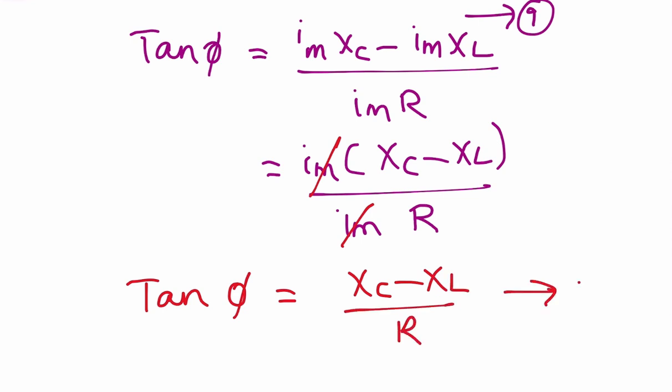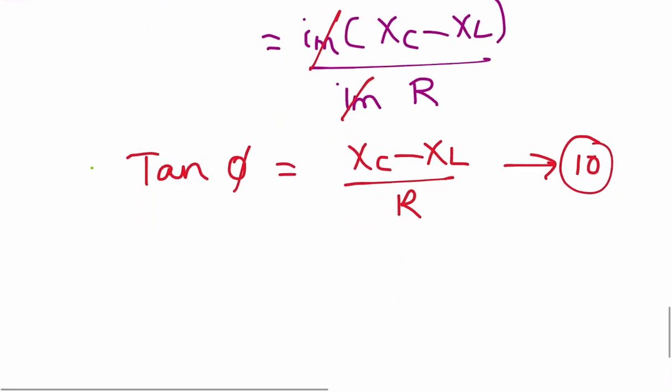So with this phase difference, with that peak value of current, you can know the equation of the current, that is I is equal to Im sin omega t plus phi. Now if you see the current equation which we already wrote, I is equal to Im sin omega t plus phi. In the beginning I told you we will come to know what phi is at the end of the discussion.